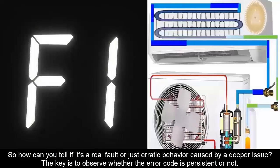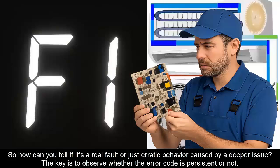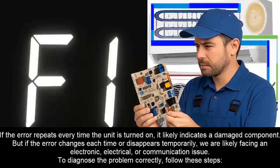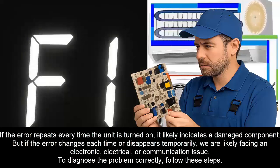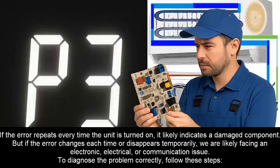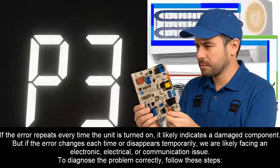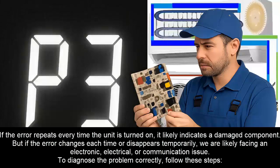So how can you tell if it's a real fault or just erratic behavior caused by a deeper issue? The key is to observe whether the error code is persistent or not. If the error repeats every time the unit is turned on, it likely indicates a damaged component. But if the error changes each time or disappears temporarily, we are likely facing an electronic, electrical, or communication issue. To diagnose the problem correctly, follow these steps.